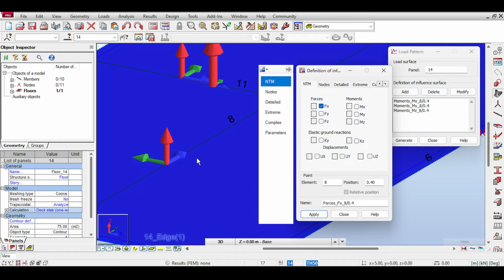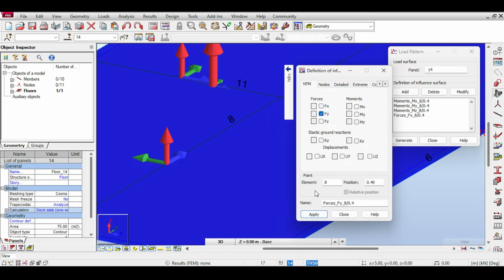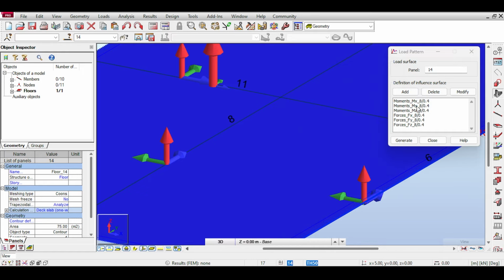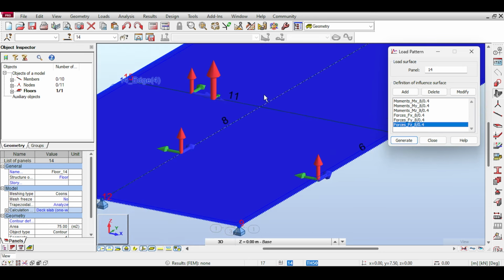Then I want to see the axial compression and tension, the shear in the y, and the shear in the z. Now, to be honest, the most important values are going to be the moment around y and the force around z, because the moment around y is the typical bending moment, and the force around z is the typical shear force. That's not everything.